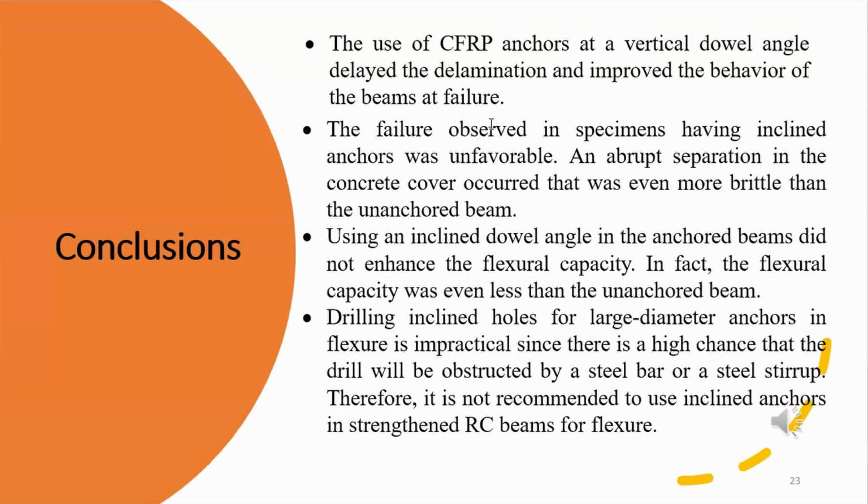And also, drilling inclined holes for larger diameter anchors in flexure is impractical, since there's a high chance that the drill will be obstructed by a steel bar or a steel stirrup. Therefore, it's not recommended to use inclined anchors in strengthened reinforced concrete beams for flexure.